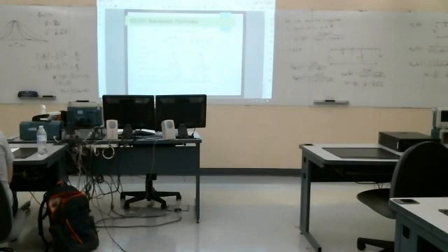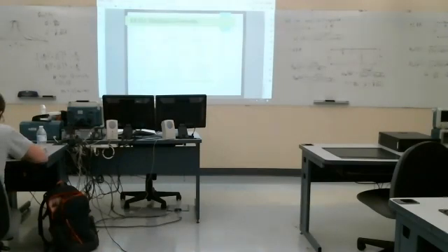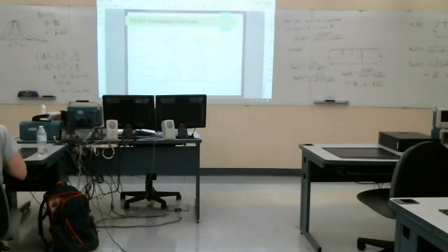So the voltage here is going to be 90 degrees ahead of the current because we're multiplying by j. The voltage across the capacitor is going to be 90 degrees behind the current because we're multiplying by minus j. So they'll be 180 degrees out of phase. That's what's going on. They're equal but opposite. So they're not individually 0, but they sum to 0. So there is current flowing, but it is a strange phenomenon. The omega, it's supposed to be numeric. Yes, thank you.